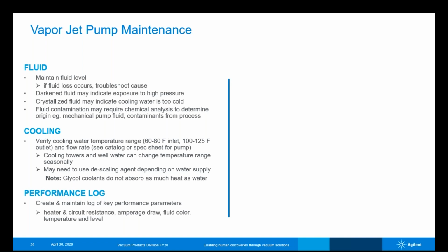If we're using water, I may need to use some sort of a descaling agent, depending on where our water is coming from, whether it's well water or city water. Also a note here on glycol coolants: they don't absorb as much heat as water does, and I think we have to take that into account when we're considering the cooling and the performance of our diffusion pumps.